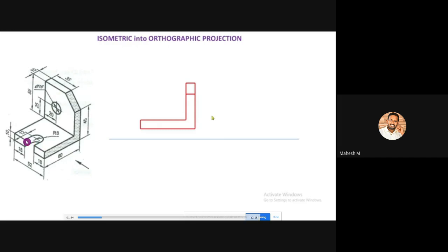Okay, so you have to mark these hollow portions with dotted line. Okay, so what is the length of this slot? You can measure the length of this slot with these dimensions. So the radius of this semicircle is 8 mm. Radius is 8. So from the center point towards the right end, it is 8. Similar to that, from the center point towards this left end, it is 12. So the total entire length of this slot is 20 mm.